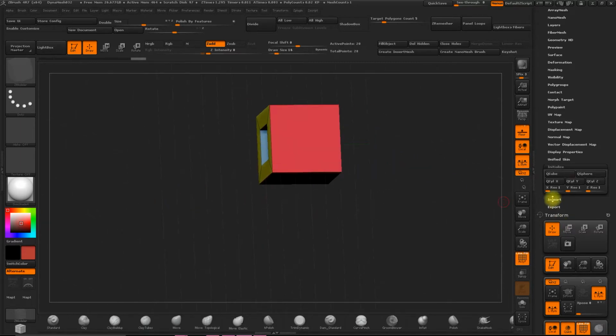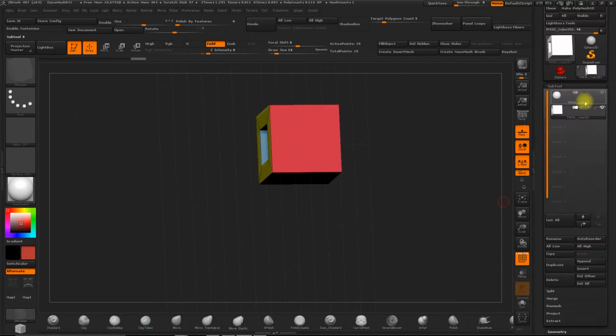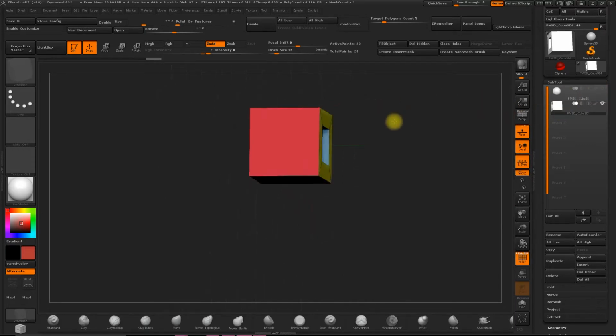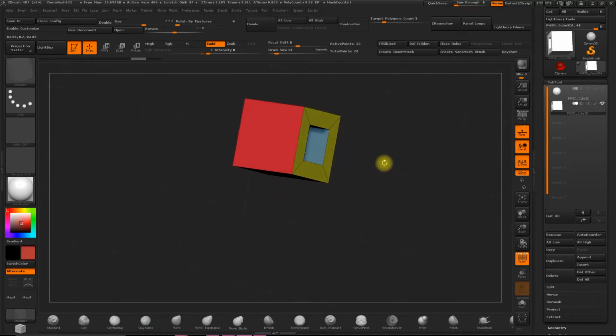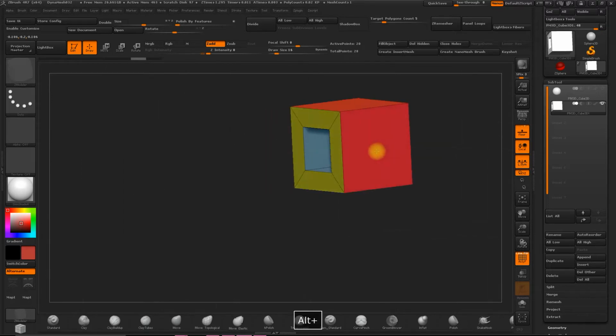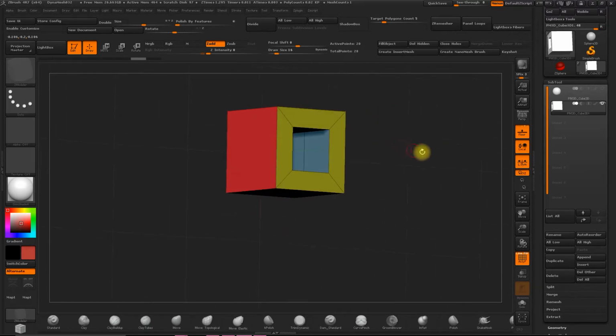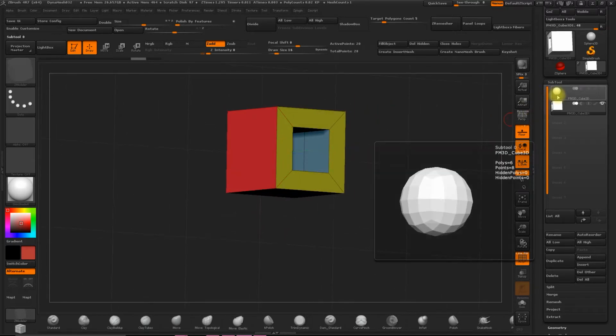Make the extrusion until we can see the other element. I'm going to cut it a second, like that. And as you can see, I go back, make the extrusion like this. And then we make the hole. That's one option of doing this element.